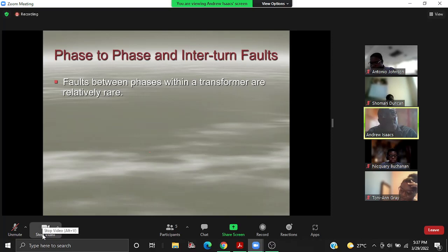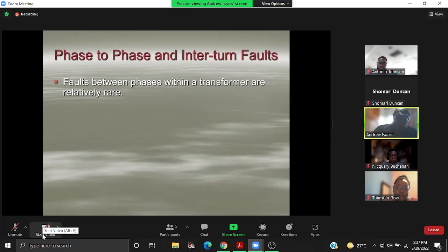Now, if we go back to the basic principles of transformer operation, you know you have a core, right? But that core, if just left as a big solid piece of metal, would increase your losses in terms of eddy currents, right? And so what is done from what you would have known from high school? Remember that thing about lamination, right?